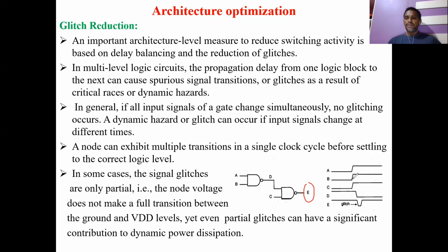Okay, but D will be reached at this point. So what happened here? There will be a problem. C is one input, which is the higher value, and D we will get only after this point. If you consider NAND gate operation, with a higher value and a lower value, you will get the lower value. Okay, but what about this time? This time will be called glitches.